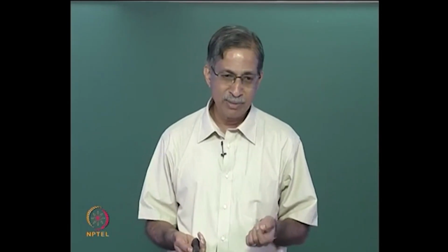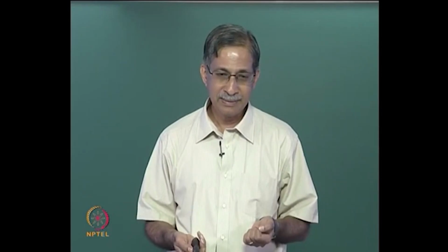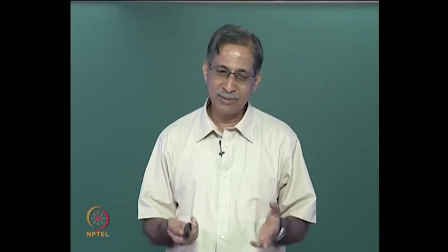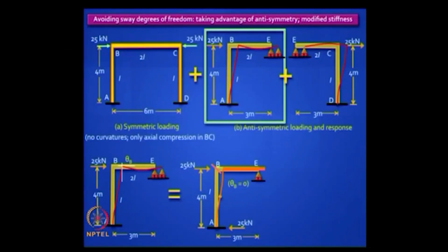Will the moments be clockwise or anti-clockwise? Well, there are many ways of figuring it out. You can look at the figure and decide. It will be anti-clockwise. Another thumb rule you can take is, whenever I have a clockwise chord rotation, I will end up with anti-clockwise end moments. Okay, we proved this earlier. So you know everything, you've got the fixed end moments.